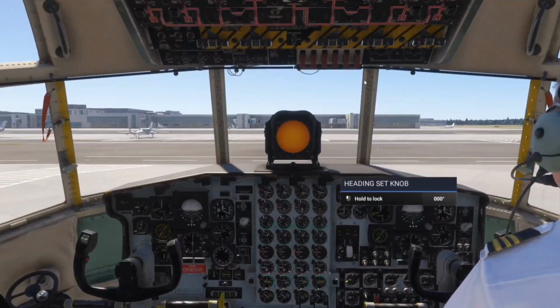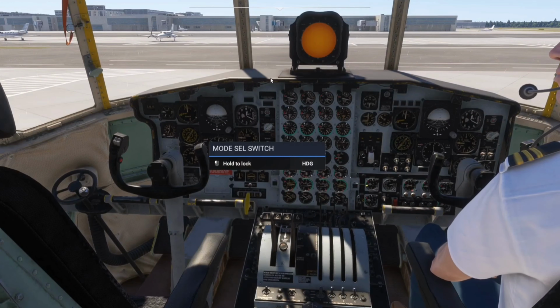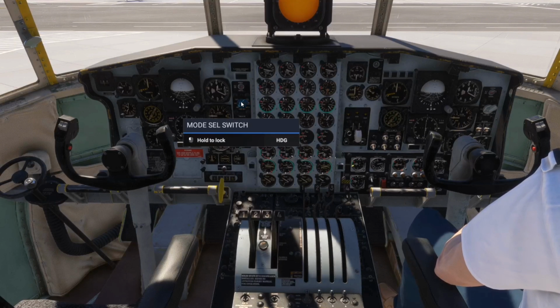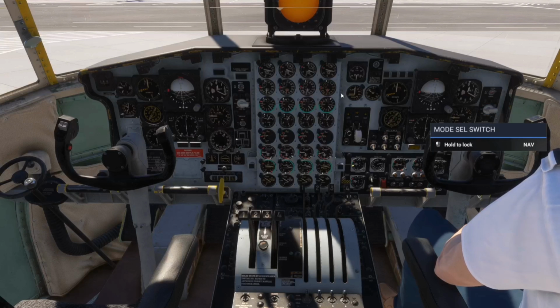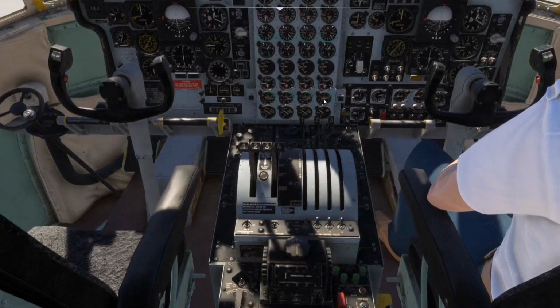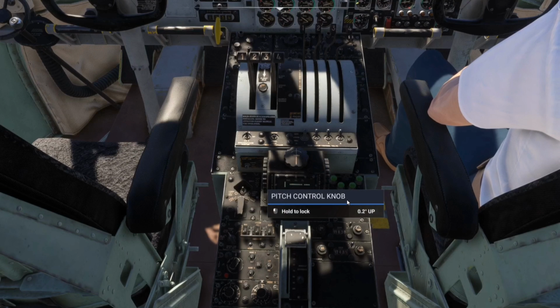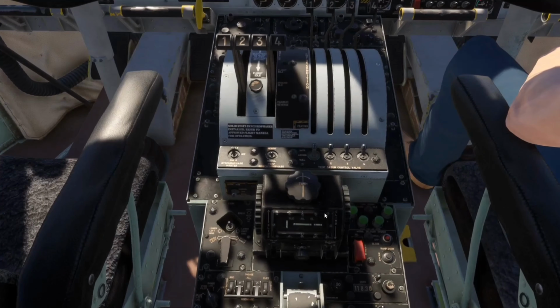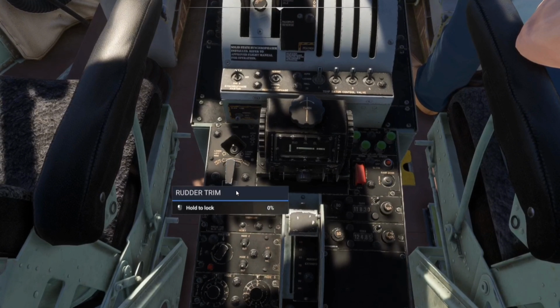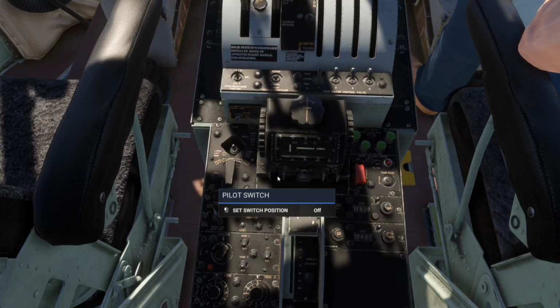So now you've got the engine started, let's actually figure out how to work the autopilot. For starters, mode select switch, change that from heading to nav. Do that on both of them, for the co-pilot and the captain's, the first officer and captain's primary flight displays, or artificial horizons. Then down here, we have this little sensor console that is for the autopilot, and we also have this little console down here as well, which is also for the autopilot.